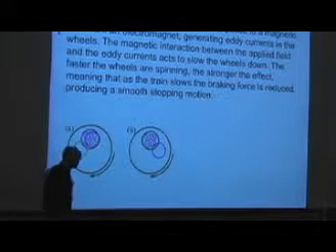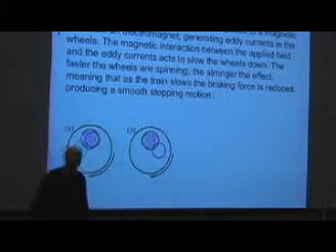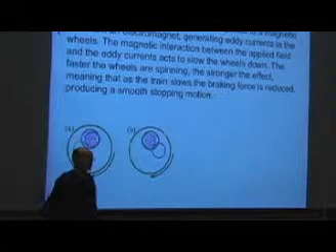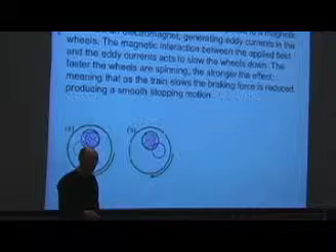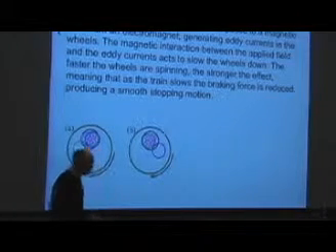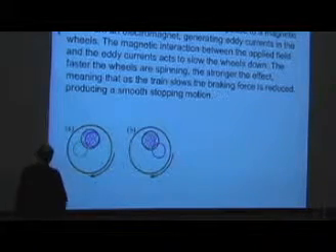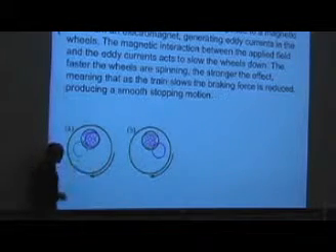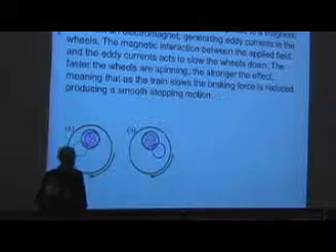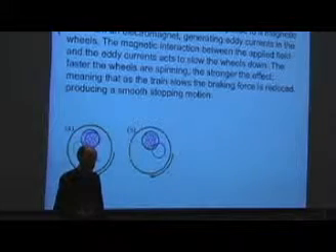So you don't use a permanent magnet, but you can use an electromagnet. So when the driver of the train presses the brake pedal, that actually switches on current to a coil, which sets up a magnetic field. And the magnetic field is set up only in a small part of the wheel. You don't want to expose the entire wheel to the magnetic field because you need to exploit changing magnetic flux.